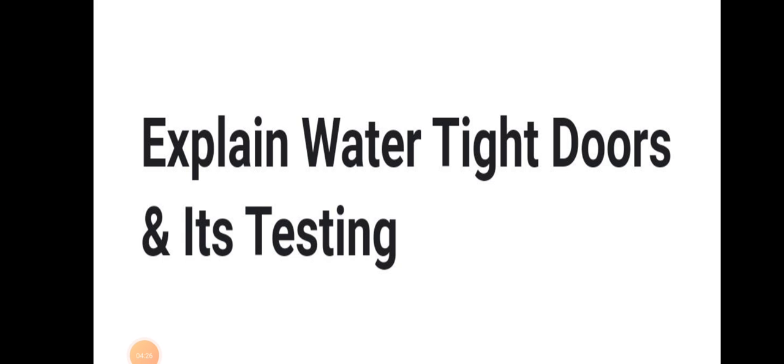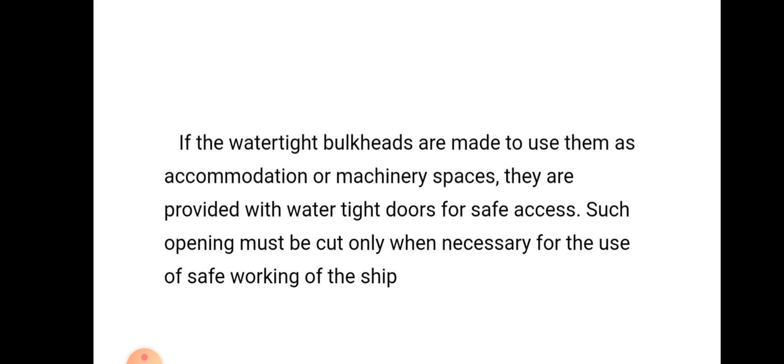The watertight doors and the testing that we need to do. So, watertight doors and their testing. If watertight bulkheads are made to use them as accommodation or machinery space, they are provided with watertight doors for safe access. Such openings must be cut only when necessary for the safe working of the ship.